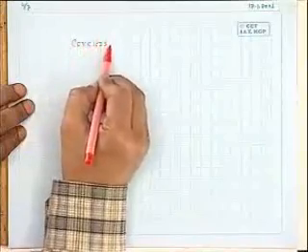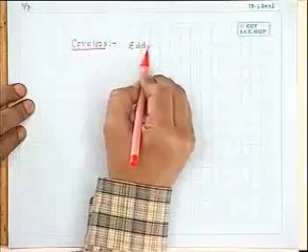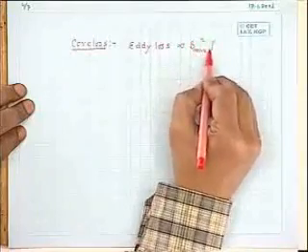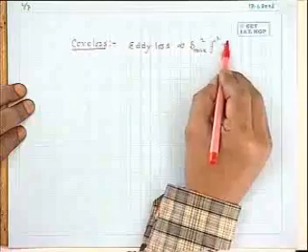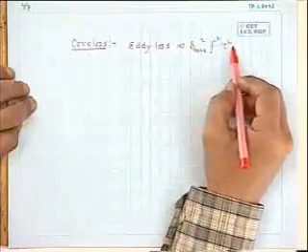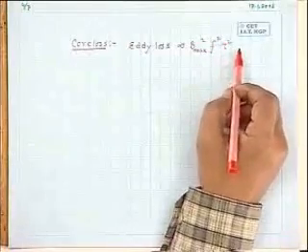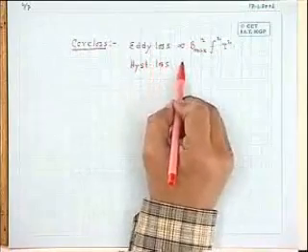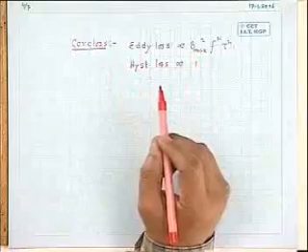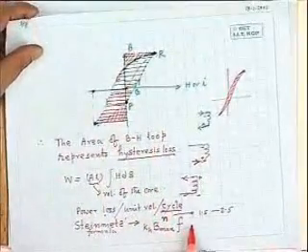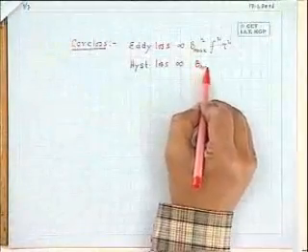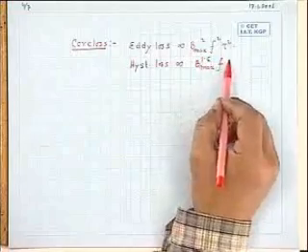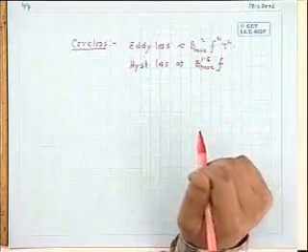Therefore, now to summarize the core loss, as we have seen, it will comprise of eddy current loss, which will be proportional to, as we have seen, Bmax square, f square, and thickness square. And this unit also, if you remember, was the amount of power loss per unit volume. If you go through earlier notes, per unit volume. And hysteresis loss is proportional to either the area of the BH loop, or if you go for this approximate empirical formula, it will be proportional to Bmax raised to the power something. For ferromagnetic material it is 1.6 something like that, into f, per unit volume.